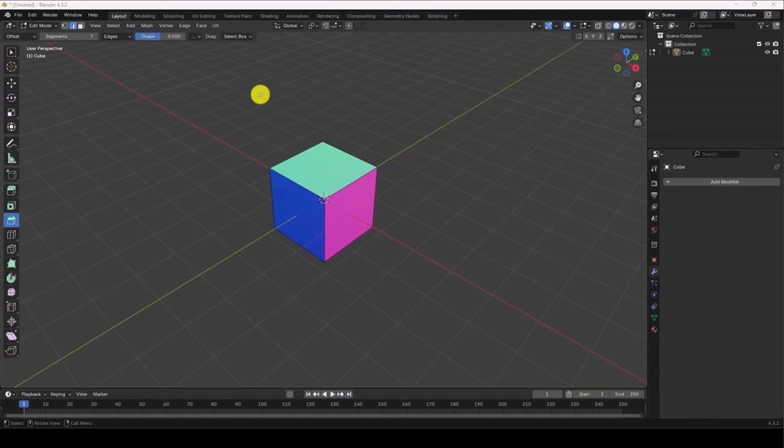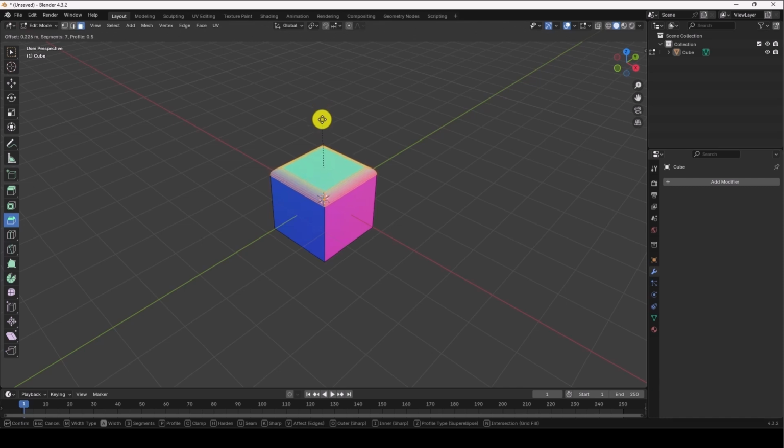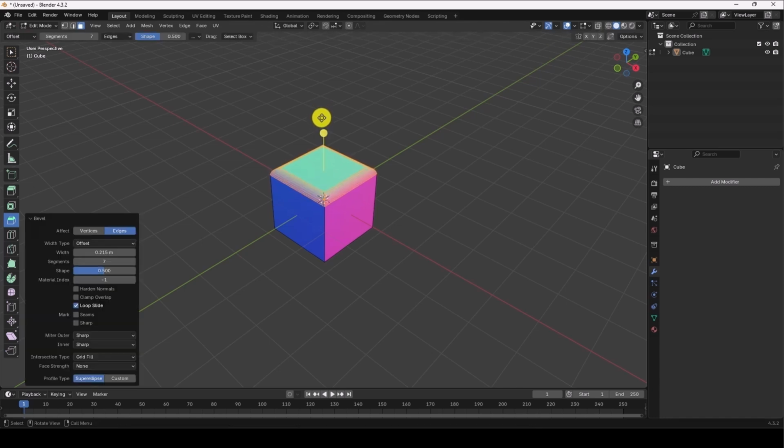The next option is Bevel, which is used for beveling or chamfering edges and corners. When I select the Bevel tool, switch to Selection mode, and select a face, I can adjust the bevel by moving the mouse up or down. This allows me to chamfer the corners of the selected surface. You can increase the number of steps here, to create a smoother bevel. Additionally, you can adjust the width of the bevel or chamfer. You also have the option to control whether the shape is concave or convex by modifying the profile settings.